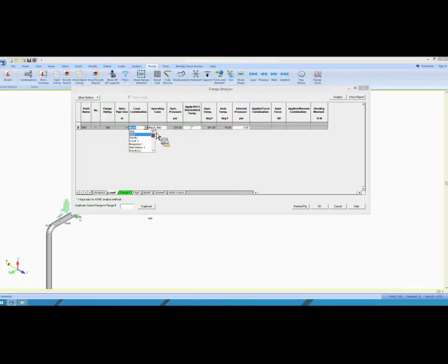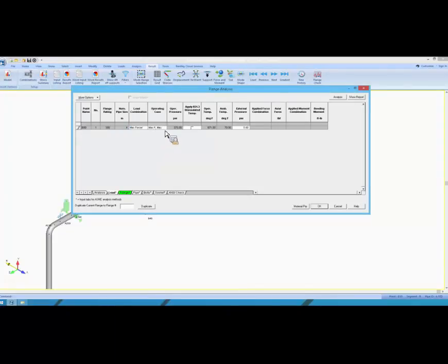So you have the load combination which you can select. These are all your non-code combinations that are available here. Let's select maximum force and maximum movement from among all the combinations. The operating cases we would set to maximum P and maximum thermal case, so it would show the operating temperature and the operating pressure. If you want to enter any external pressure to be incorporated into the calculations for the flange stresses, you can enter that here.